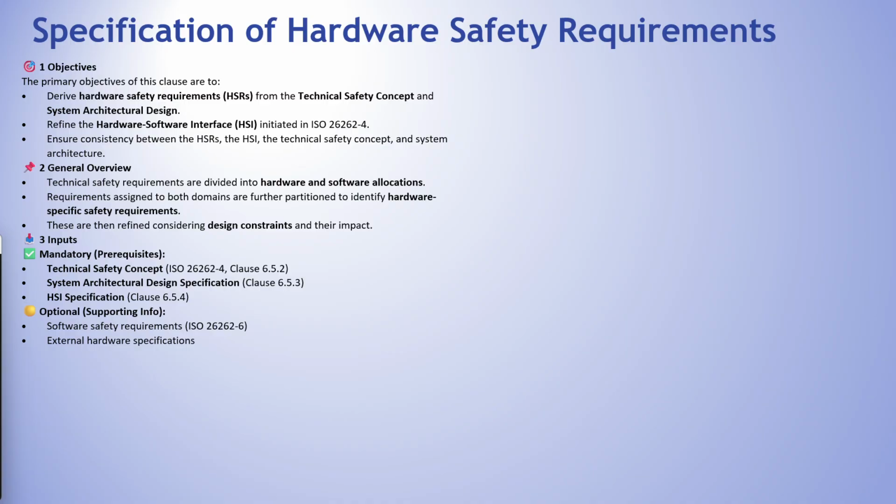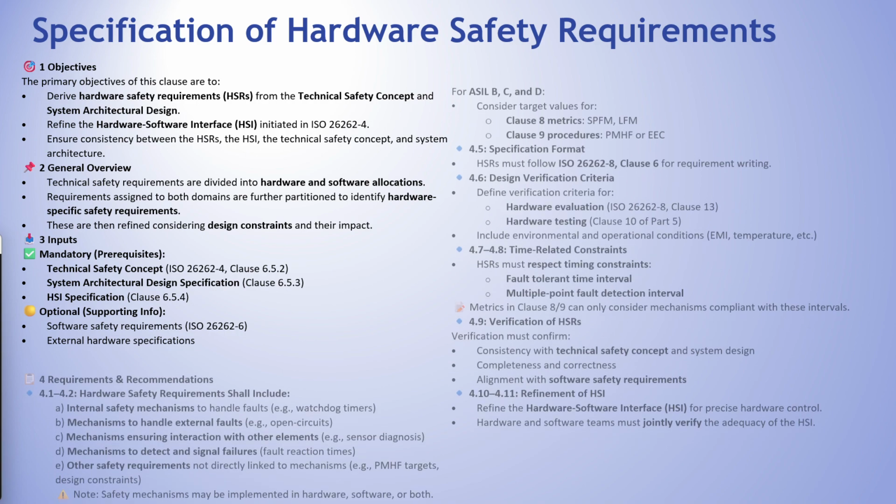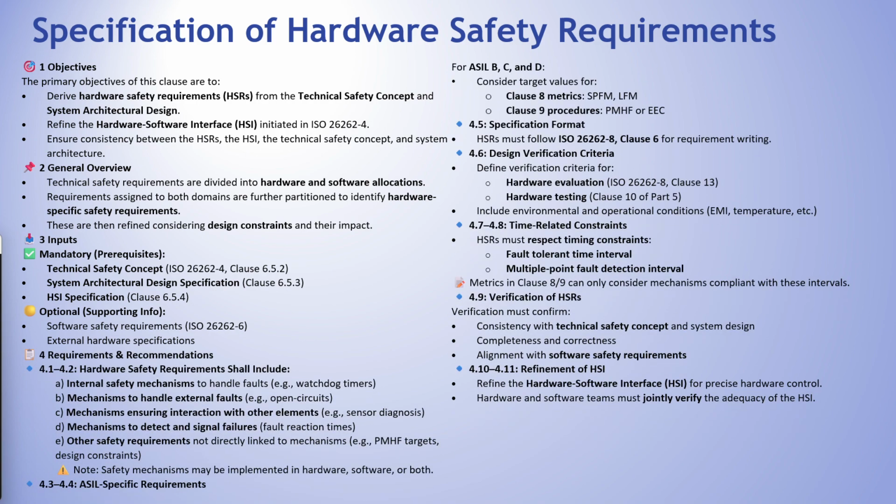Think of it like breaking down a big safety goal, like prevent unintended acceleration, into super specific things a particular chip or sensor must do or must not do. It also spends time refining the hardware-software interface, the HSI, which is critical because hardware and software have to work perfectly together in these systems. Makes sense. They're totally intertwined.